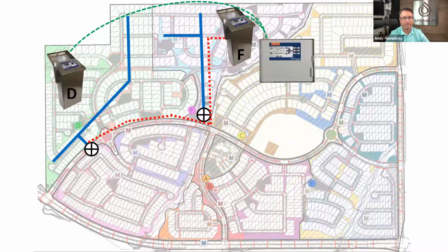I didn't know what the design intent was going into this. There's no setup here, but I can see how there wasn't a plan for a flow station necessarily initially, because they were all set up per each controller individually. And so introducing the flow station can solve that problem where they now need to be shared, but weren't originally intended to be. Right.